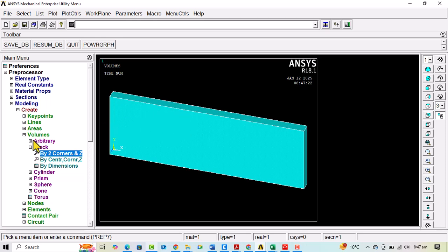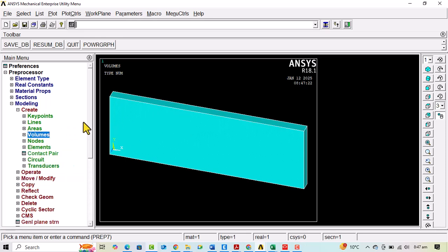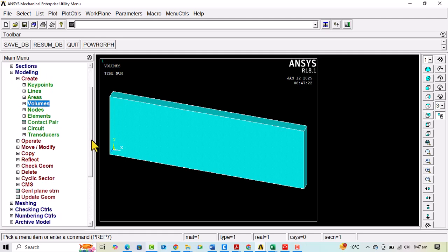Now I will be dividing it into brick units. I am considering my brick size to be 0.228 meter in width and 0.07 meter in height. In this way I will have 10 bricks in the vertical direction and 10 bricks in the horizontal direction. In order to